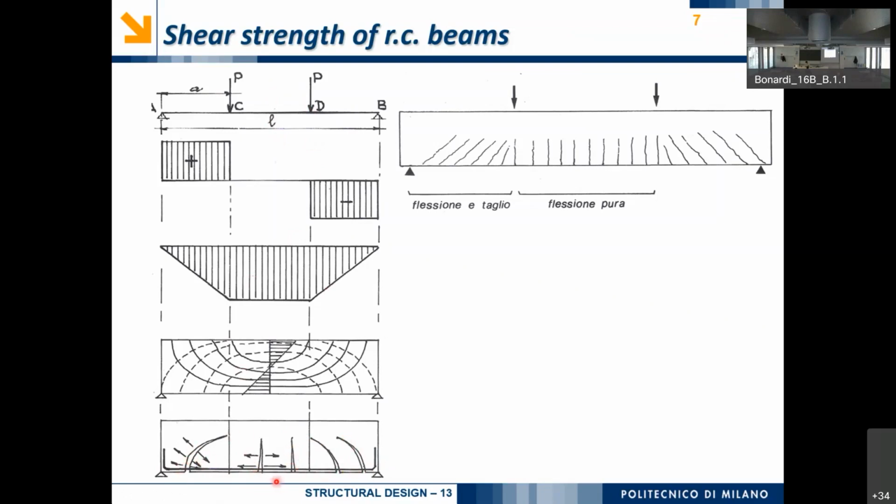cracking, in the form of crack patterns, at the bottom part of the structure, and the path of these cracks is quite peculiar, and it is something like that. Now, if we compare these, basically, we can discriminate two different behaviors of the cracks. So we have one region, the central region, where the cracks are purely vertical, and it is better highlighted here.